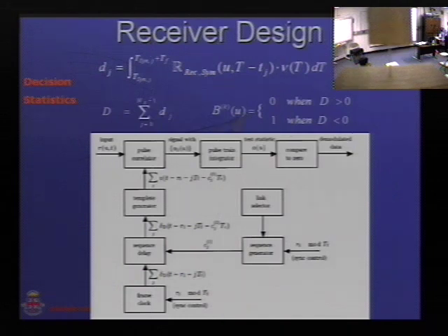Here I just keep talking, first introducing this background. At the receive side, as usual in the communication system, you just compute the autocorrelation of the received information with a jitter version, and the one generated locally, and try to see where it has a peak. Look at this delta. It looks through this NS; it's not just looking once, because one cannot make the decision. You look at several of them, say hundreds. Then, based on the majority, you say, okay, if the D is greater than 0, it's called decision statistics. If it's greater than 0, you say the transmit is 0, versus it is 1.